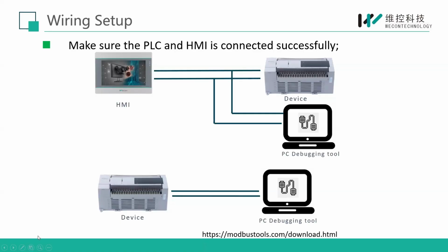Okay, so you can use the PC debugging tool instead. So this is Modbus Poll and Mod Scan. Okay, so you can read the direct data of this PLC in our Modbus Poll and check where the problem is. You can do it also in PI Studio. Instead of this debug tool, you can use PI Studio and do an online simulation. Okay, in PI Studio we have one option regarding online simulation, so you can also check it from here.